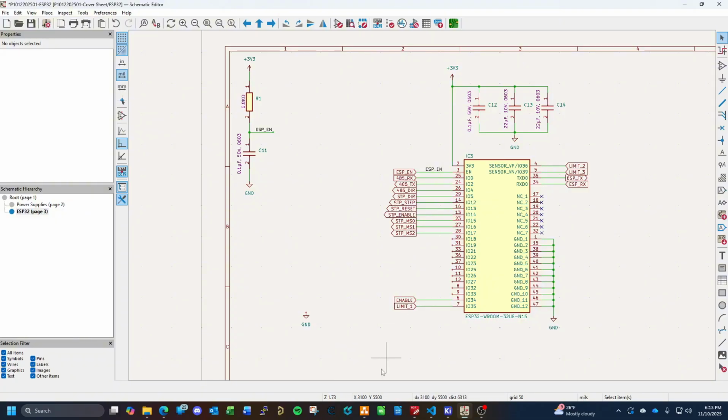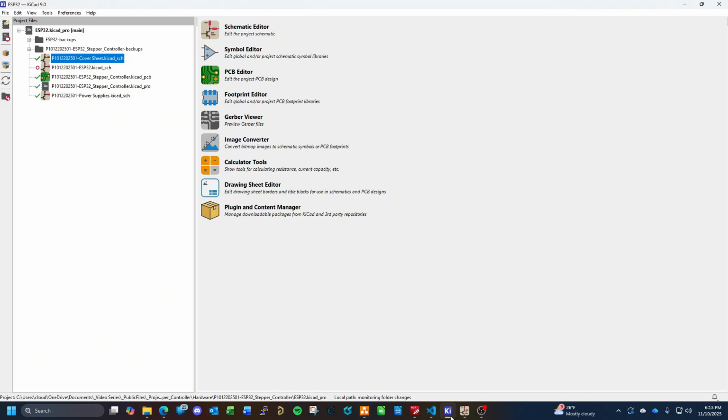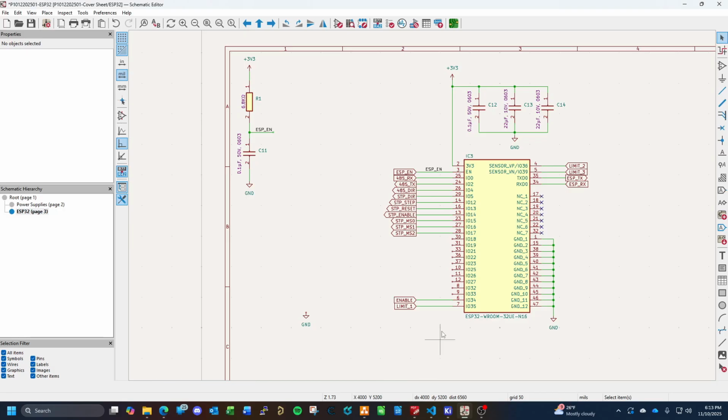That'll also give us, let's see here. So that's our stepper driver. That's step, direction, reset, enable, microstep 0, 1, and 2. They call it mode, but microstep just makes more sense to call it that for me. That way we know what we're setting up, what we're programming.